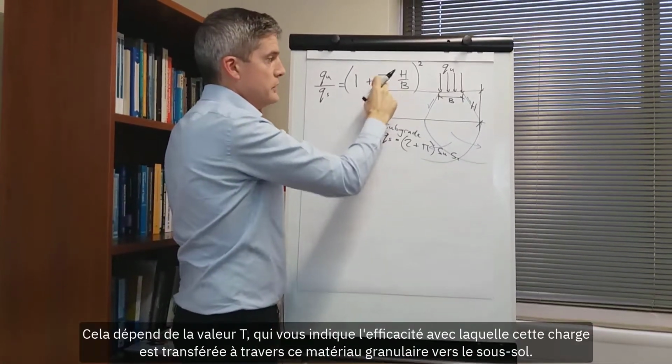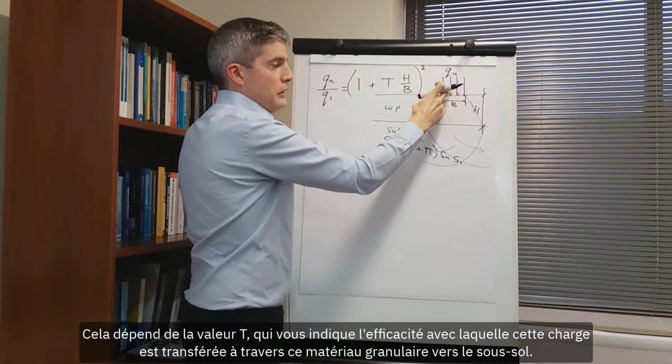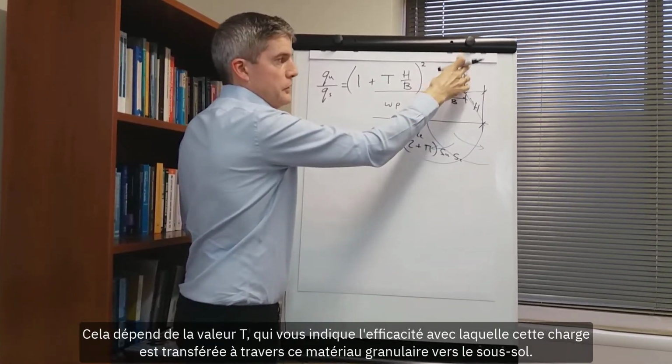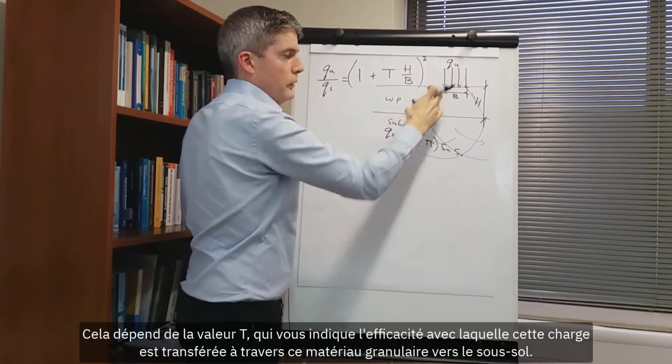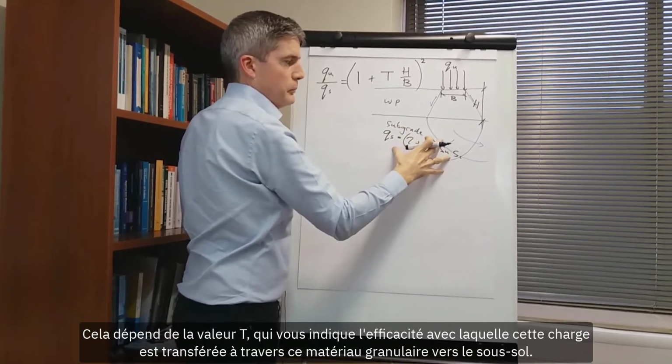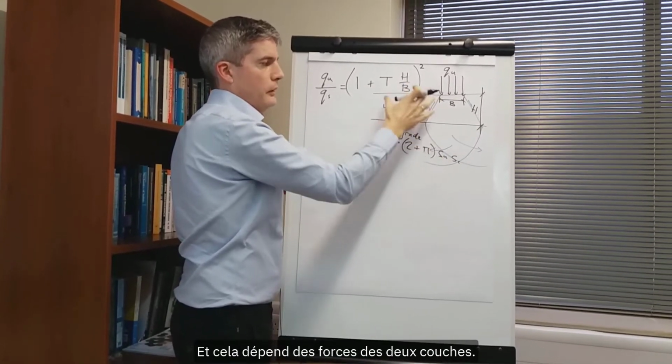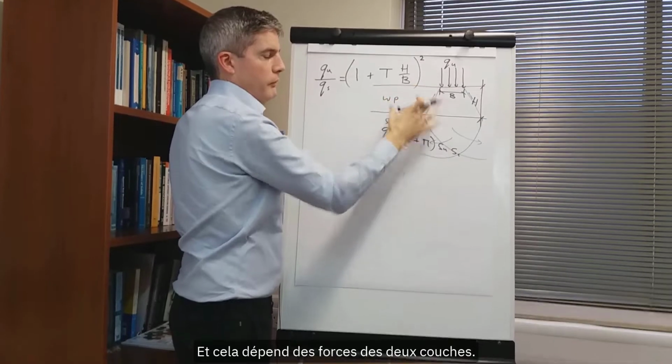It depends on this T-value, which tells you how efficiently this load is transferred through this granular material to the subgrade beneath. And it depends on the strengths of the two layers.